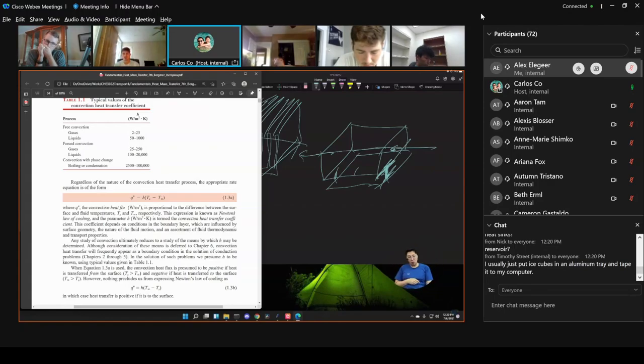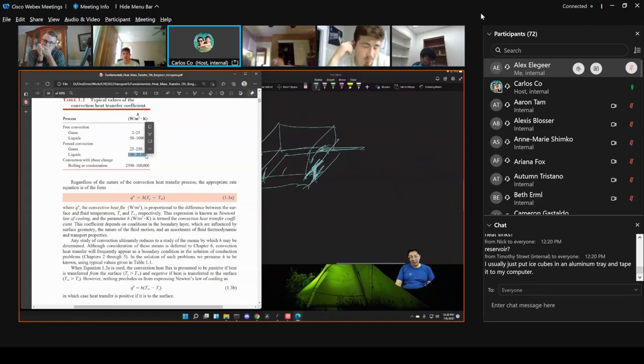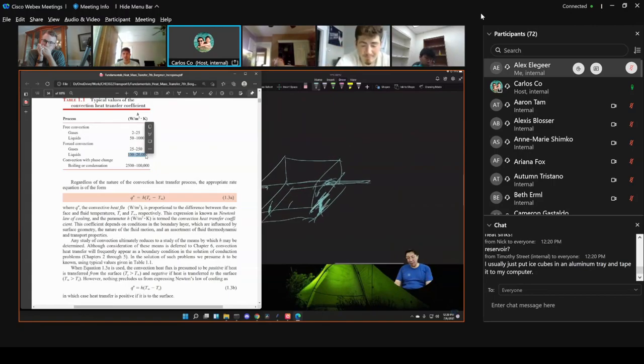And so when liquid passes through it and passes out, the effective heat transfer between the chip and the liquid becomes something done by convection. And that can be considerably higher depending on the flow rate of the liquid. Now you might ask, well, wait a minute, I'm not going to have a bucket of cold water continuously passing through my chip. No. And so what happens is eventually this water, or that coolant liquid, is passed through something.